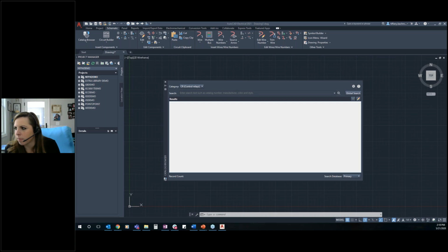This one here is by Mark, and I don't think Mark Hagerman is on. When files get moved to a recycle bin for low permission users, is there a way to stop the XREFs from getting updated to make the relative path to the new location? That seems more like a general AutoCAD question, and I think we might have tackled that one in that meeting. He had a lot of XREF things going on. I don't know if that's going to be applicable to everybody here. It's atypical to use XREFs with AutoCAD Electrical. I'm not saying it doesn't happen, but it's an atypical workflow compared to others.